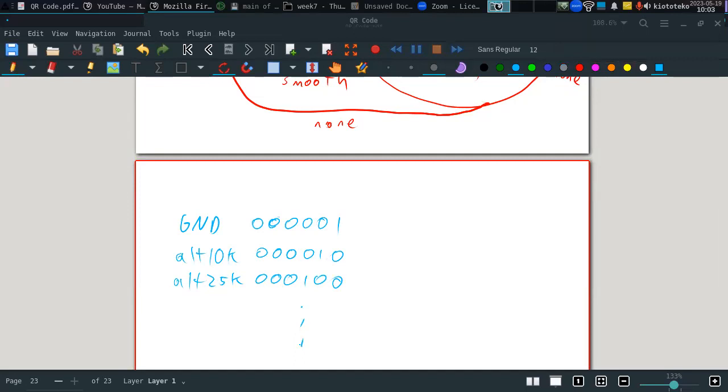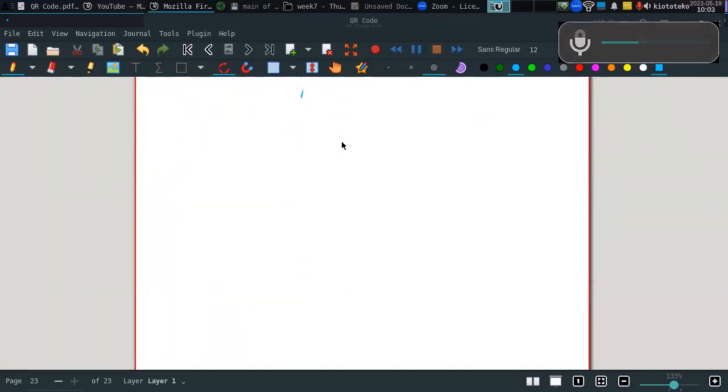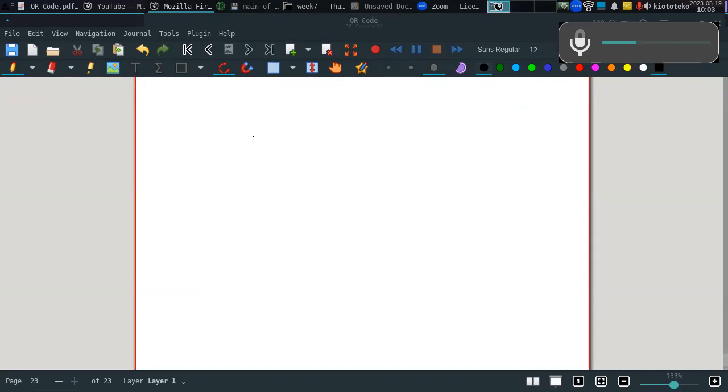So based on this, the first thing would be to use a truth table. Although in this case, we won't do the truth table we were doing before because we will have a lot of columns and rows, no? Because now we're using 6 bits to represent the state. In fact, not all combinations are being used, so we don't need to do that. The way we are going to build our truth table will be the following way. We put here the combinations of our states.